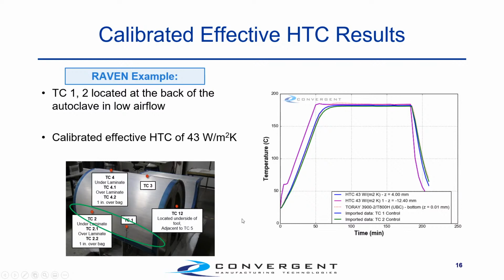Now what's important to see is that we do see these variations on the parts, and so calculating a local HTC is important for the most accurate results. And what you can also do with this is bound a problem by capturing the areas with the lowest and the highest HTCs, and now you know that you can simulate other positions in here within that bound.